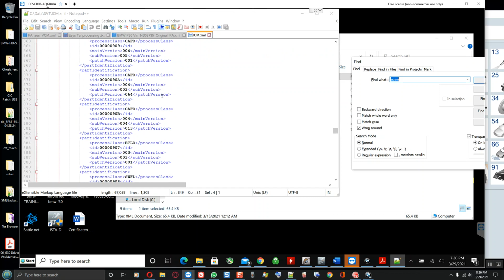So the SVT is the control unit 3, where their control unit description, model IDs, those process classes with their IDs, are determined from factory. And that is why I said if the advanced crash safety model was from factory, it will come with original SGBM IDs, which are those files called process class, with their respective IDs. That is what makes up the vehicle order. They determine what those file IDs will be for the kind of hardware variant that will be on the car.